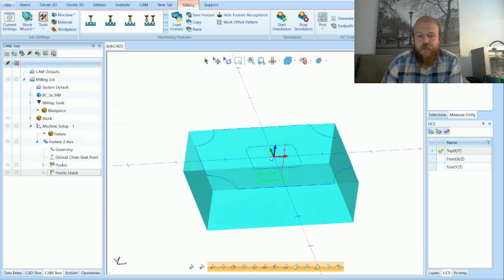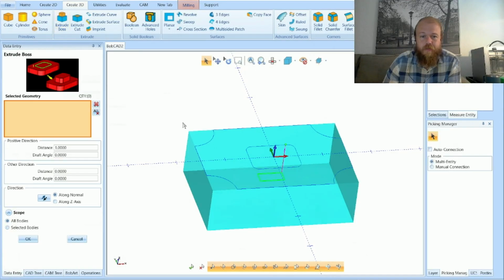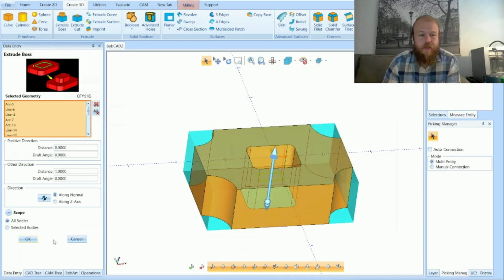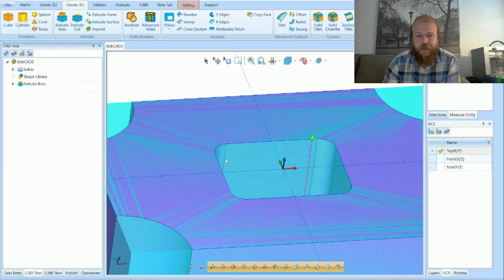Now that's our geometry selection. I'm sort of going over geometry selections and how to program for lathe. Now 2-axis, we're just selecting either wireframe, or if I had the 3D model, then I would be selecting the surface edges of the surfaces on the top here, or the wireframe that I had before.